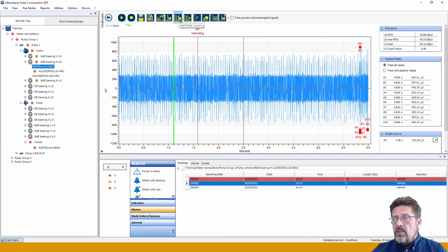The next one is your delta cursor. Delta cursor is very useful during your analysis. Sometimes you will define one rotation in your delta cursor and then see it here, or see the delta between two events. So simply click on the tool, select the tool and place it somewhere. Now you have D1 and D2. D1 is leader. If you move D1, as you can see, the delta time stays the same. So I move D1 and put it at a certain position. D2, if I move D2, I will change the delta T, the delta between these two.